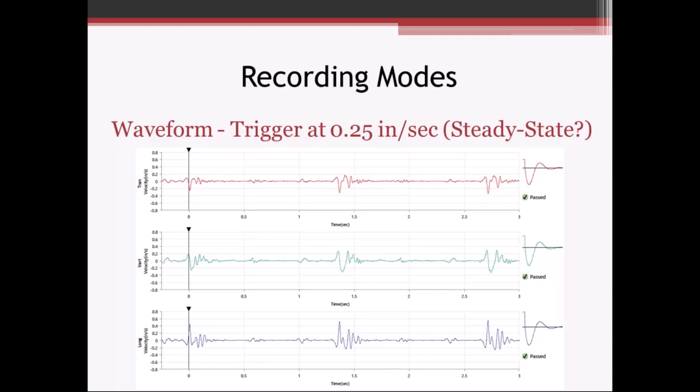So it makes sense that those surface waves, those Rayleigh waves that I mentioned before that have the highest energy transfer, the longitudinal direction is going to pick that up first, and it's going to have the highest magnitude. So that all makes sense. We've got hammer blows about every 1.5 or 1.25 seconds or so.